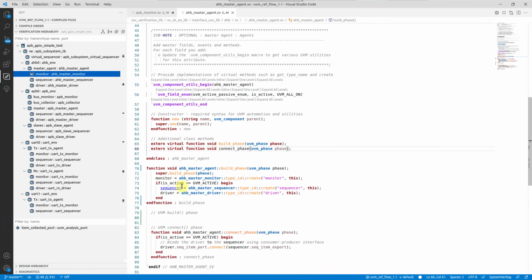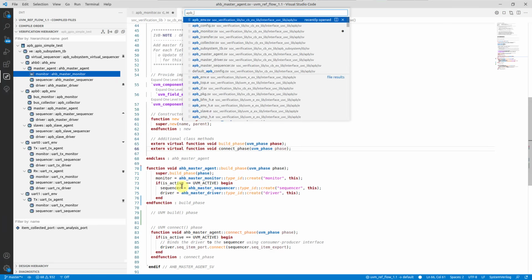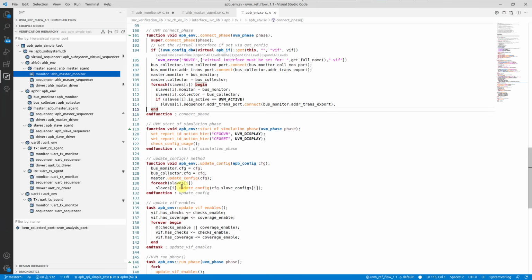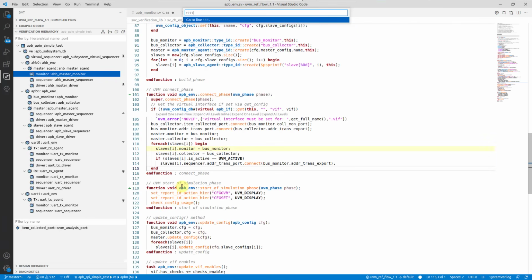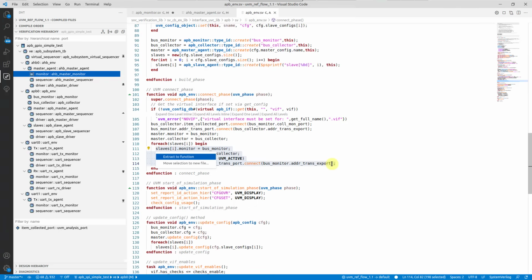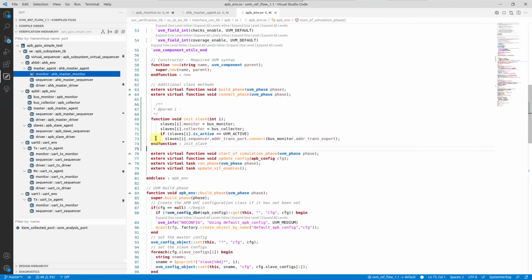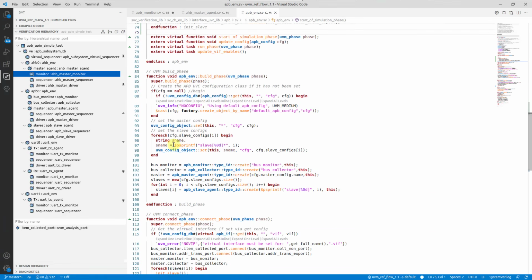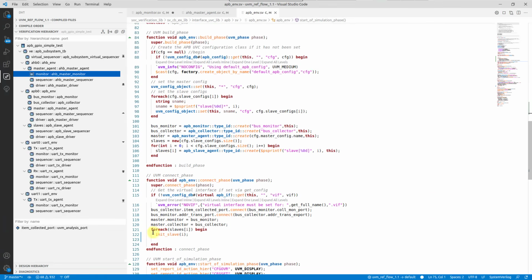Test benches grow over time, and without maintenance, code tends to become more and more complex and harder to maintain. Maybe a function grew excessively and it's time to split it up into several new subfunctions. That's where the extract functionality can help save some minutes of tedious work. Simply select a fragment of code and run the refactoring command. Then, pick Extract a function and type in the function name. Notice how the initially selected code was replaced with the new function call.